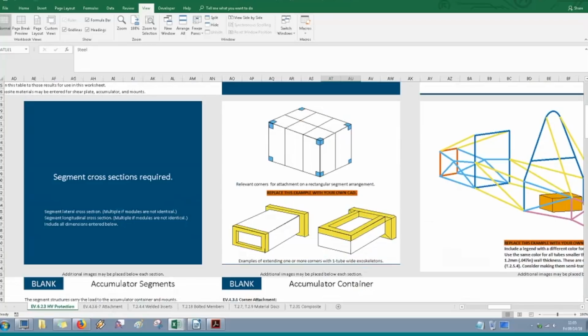And you can make that structure bigger by adding a perimeter of tubes, one tube thick. That can help you stretch it out so that it can meet your pickup point. Or if you're doing a composite accumulator, you can increase the core thickness, both in your interior walls and your exterior walls. And that'll help you tailor your accumulator size to the rest of your chassis and to meet your pickup point.